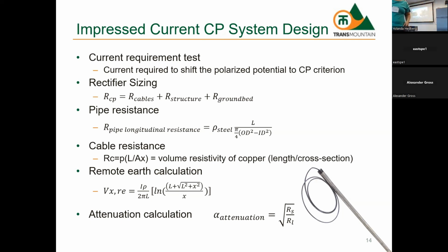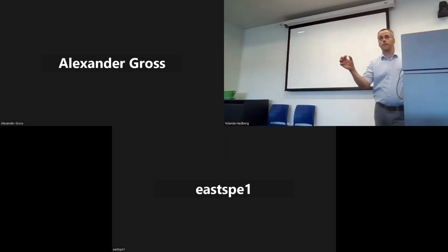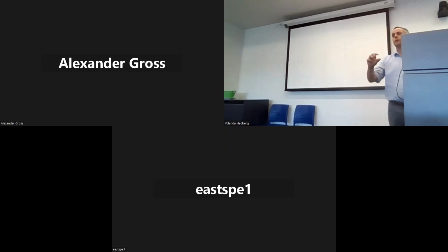Yes, you create hydrogen. Yeah. And hydrogen atoms, when they link up, create gas. And that then bubbles and can affect your coating. But it's not the hydrogen, it's the hydroxide, right? Which increases the pH. Yeah. And sometimes the pH can affect the adhesion of the coating.